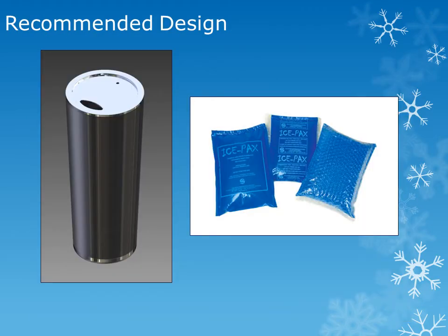In our recommended design, you could take a standard thermal mug and insert liquid in between the walls, which could then be frozen to cool the beverage. The exterior wall of the cup would be made up of a compound that is less thermally conductive than the typical metal, to keep heat from entering the system. Lastly, the interior of the cup would have increased surface area due to a bumper spiral design to dissipate the heat faster.